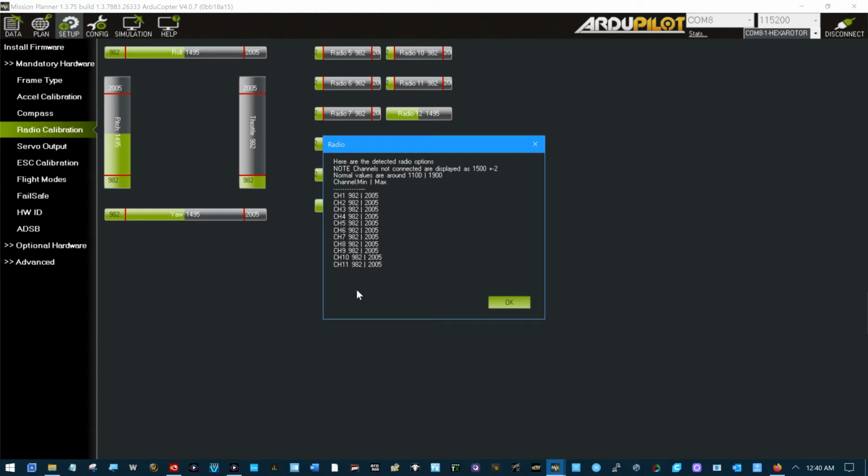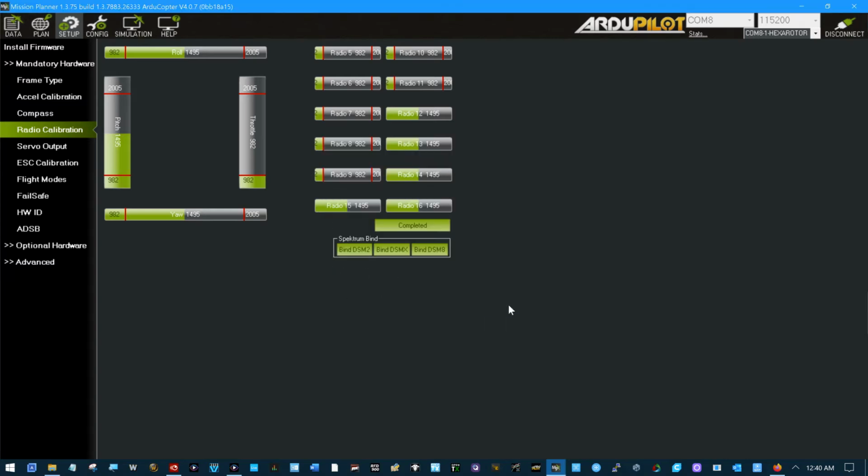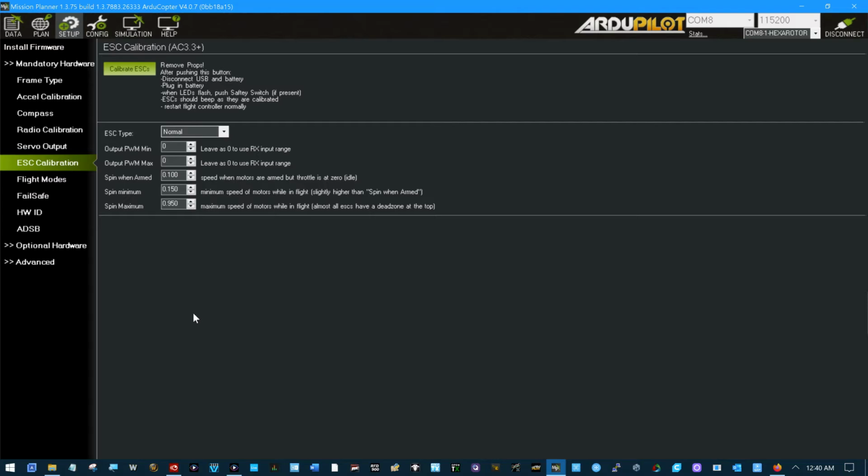So now we're still talking about pulse width. Let's follow this pulse width to the ESC. Here we're coming in for the gold. Home is in sight. Now right now, with the ESCs I have in this platform, I can click up here and choose an ESC out of this list. And I did this with the flame wheel, which is what's connected to this Mission Planner right now. And I click Calibrate ESC.